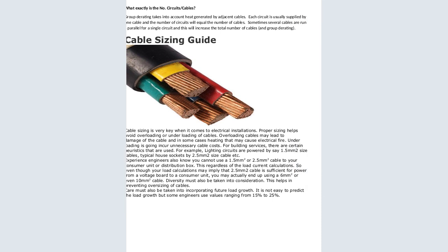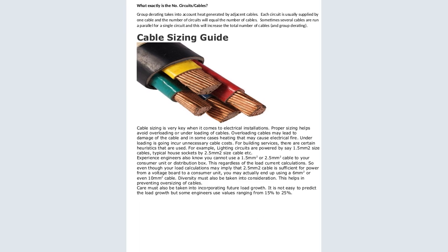So when the calculations are being done for these installations, we have to make sure it is taken into consideration that there may be future load growth. As I had started saying, there are several software packages on the market that will help us to calculate the cable size. You just put in the loading, and it will generate the size of the cable that you need for a specific installation.